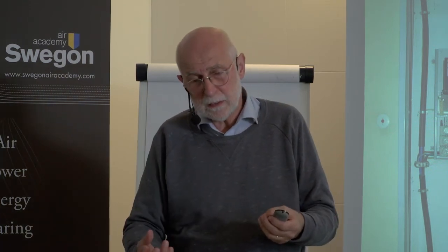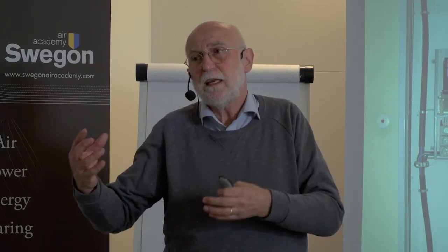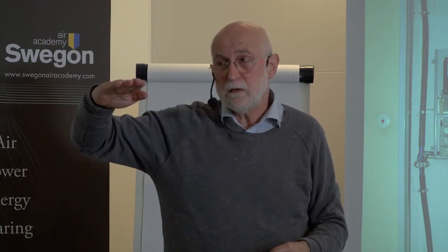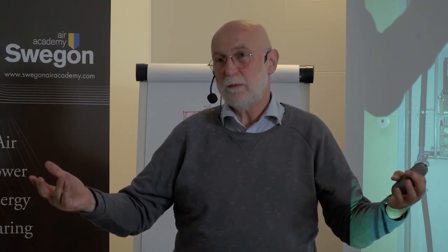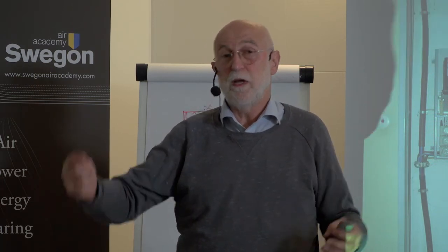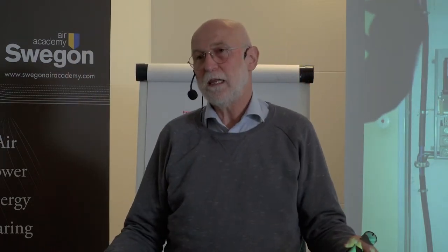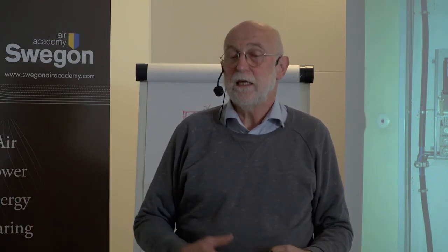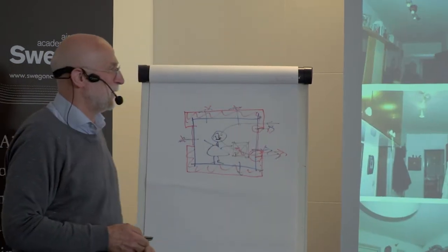And this was the basic passive house idea, to heat with air, and the heat load cannot exceed 10 watts per square meter. So if we keep the heat demand below 10 watts, we can heat with the air. And therefore, in this case, it was cheaper to have a very good building shell and not to install a water heating inside the house. And we got the allowance to build a passive house.